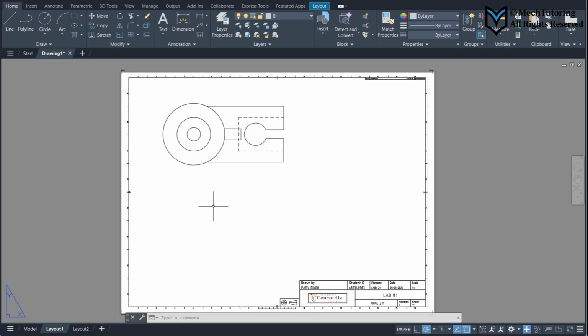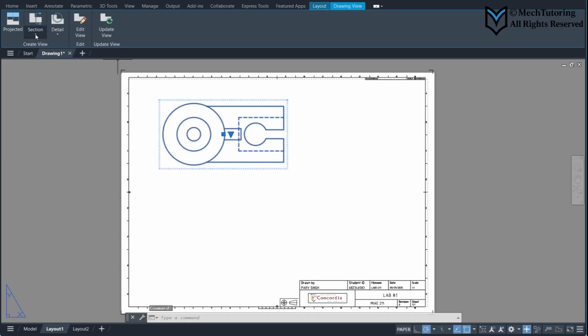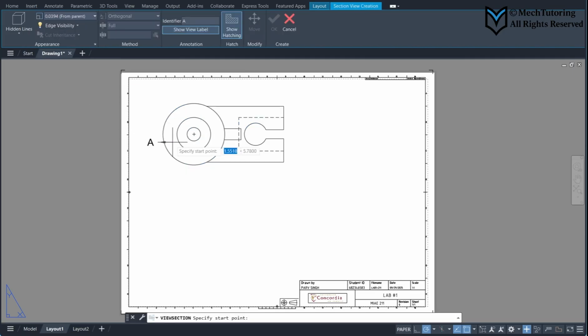Now let's create the front view. I will keep it a section view because there is a requirement in the lab manual for exercise 2 that one of the views has to be a section view, okay? So I will choose the front view to be a section view. To create the section view over here, you will click on the view and say section. And then you will say full section and hover over this node, just hover, not drag, okay? Then go to the left and click here, and then go on this side and click again.